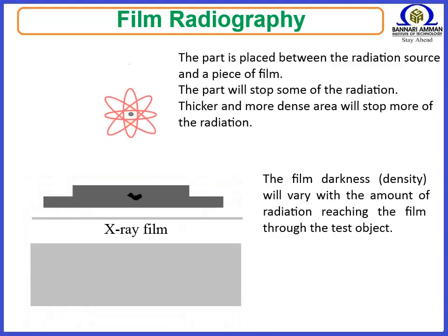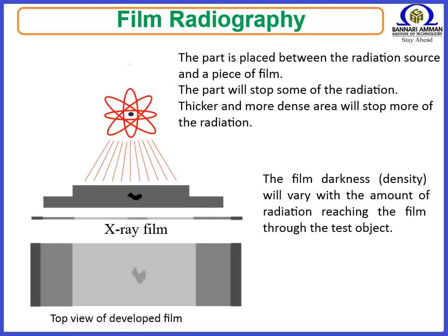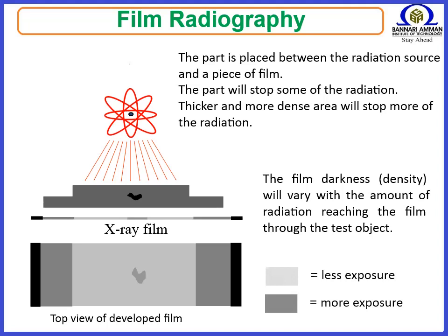Film radiography uses a film made up of a thin transparent plastic coated with a fine layer of silver bromide on one or both sides of the plastic. When exposed to radiation, these crystals undergo a reaction that allows them, when developed, to convert to black metallic silver. That silver is then fixed to the plastic during the developing process, and when dried, becomes a finished radiographic film.